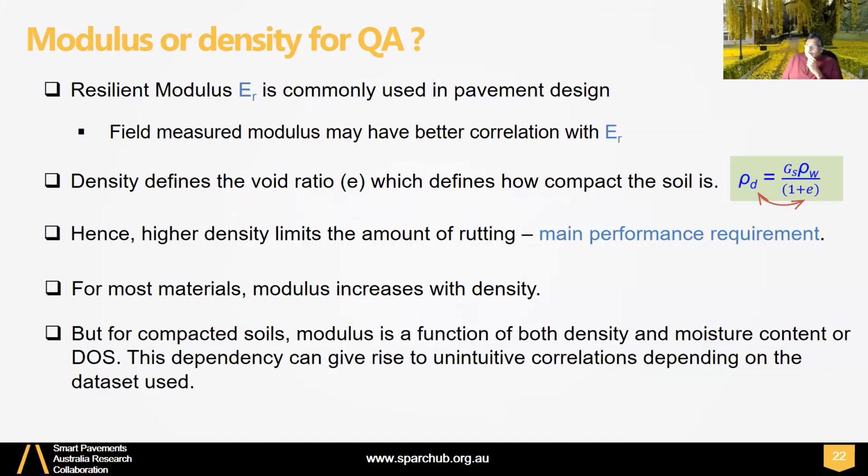Yes. And then there's another question regarding climatic effects. Only rainfall is considered, which can be accumulated by soak CBR. There may be an effect of temperature on the rutting of road surface as well as on road performance, isn't it?